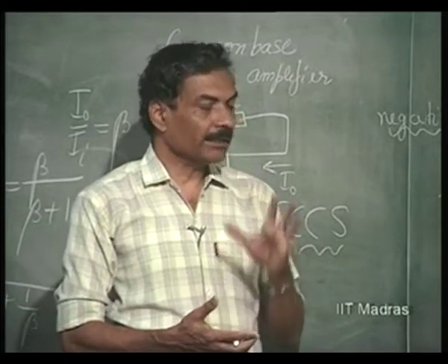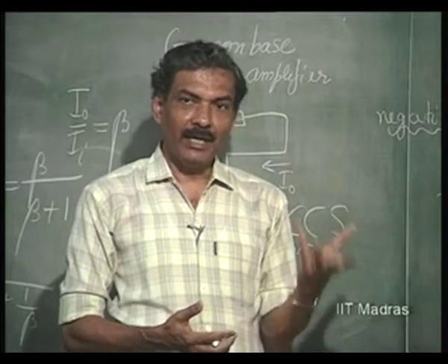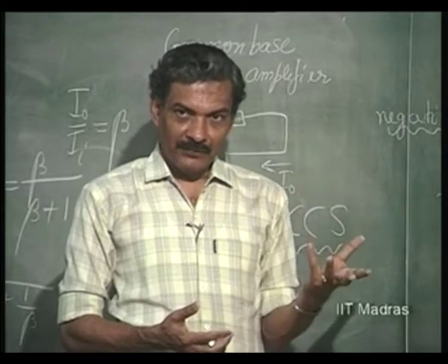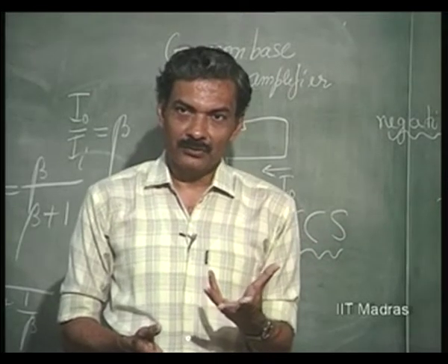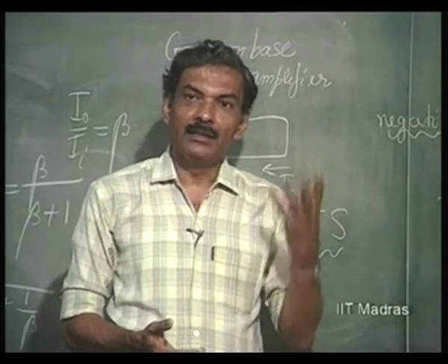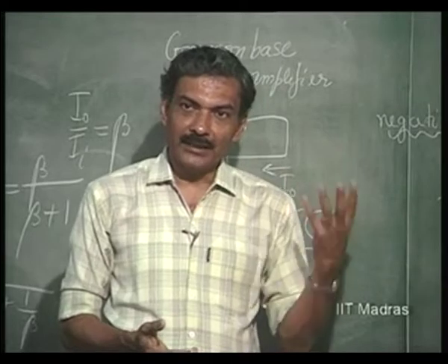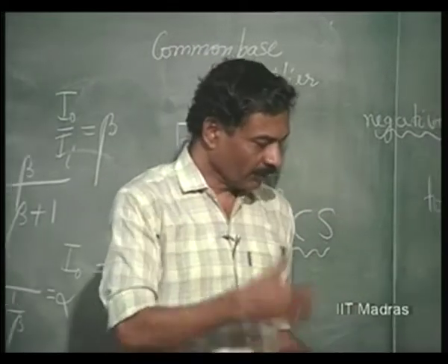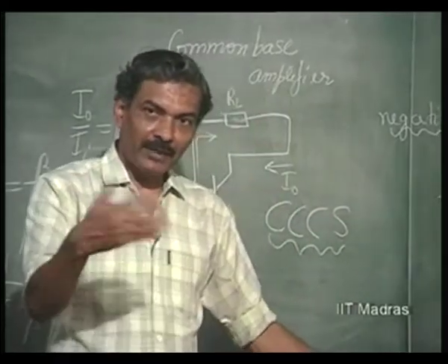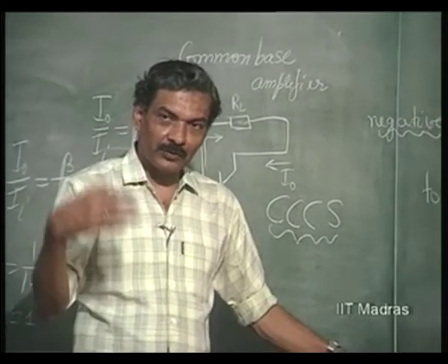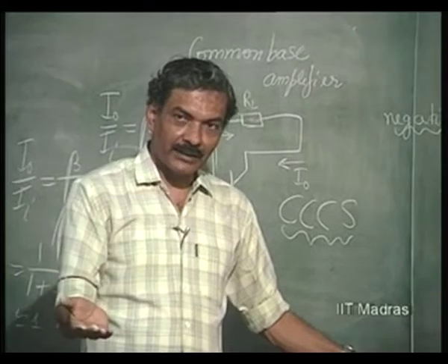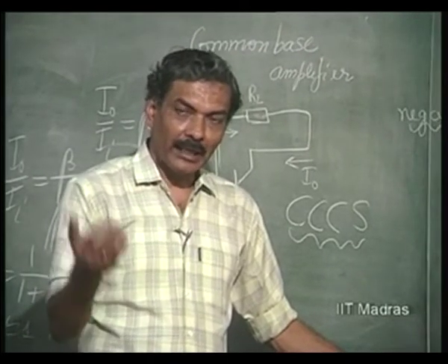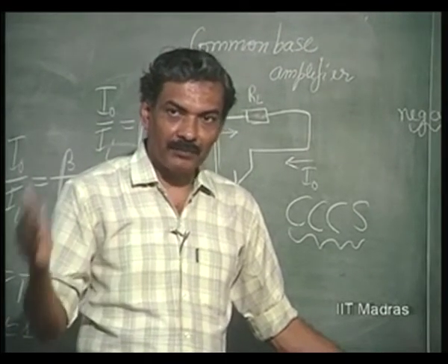So, please see that if you use a pair, Y and Z feedback will be automatically positive. A pair can only have H and G as negative feedback, so on and so forth. So, the odd number of stages will always be suitable for Y and Z feedback, even number of stages are always suitable for H and G negative feedback structures.